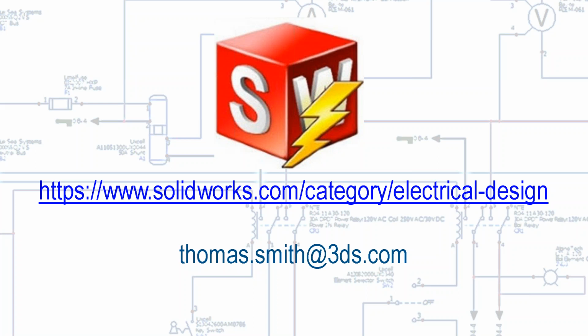They ask, can you also import AutoCAD Electrical blocks and components that have been created? The answer is yes. We have an import wizard that allows us to select a folder or individual blocks that were created in another CAD tool. Then it allows us to map those attributes into the SOLIDWORKS Electrical attributes, and that symbol is imported ready to go. Depending on how it was created, there might be some cleanup, but there are some great tools. We can import your title blocks, your symbols, your footprints, your manufacturer's part numbers. So yes, all around.